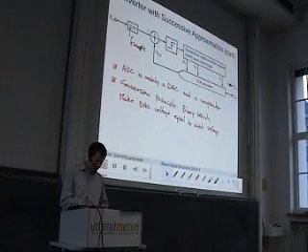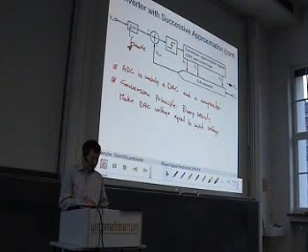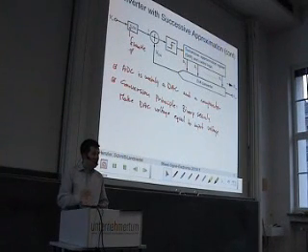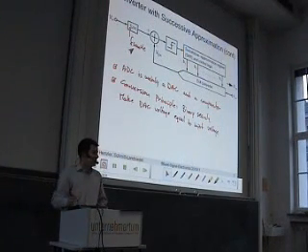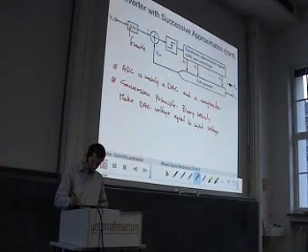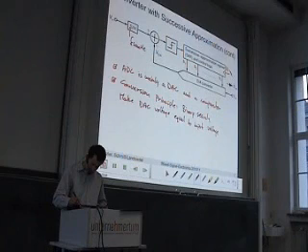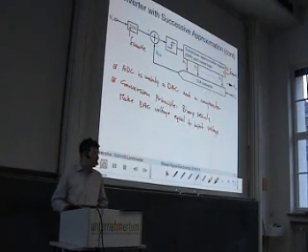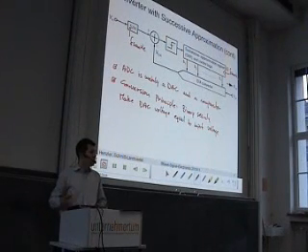If we sample here the input with a certain sampling frequency, then for each period of this sampling clock, we have to perform n cycles. So everything in here, the logic and the DAC, works with a higher frequency, which is n times f sample. So internally, the speed is much higher than the sampling frequency.